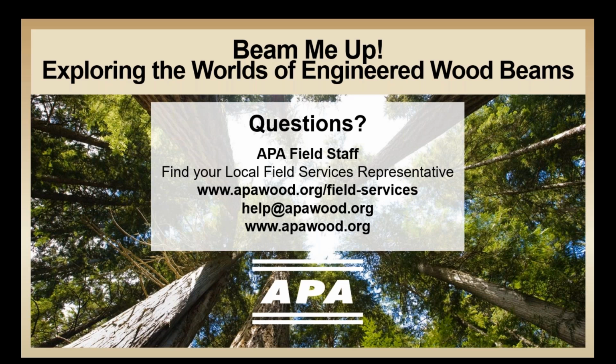They're often good. But when you think about the wood being like a bunch of straws, it may be better to use a lot of smaller connections. So nails and screws may be preferable to bolts, where you're putting that big bolt through and trying to pull those straws apart. So that's why there's a strong preference for nails or screws right now.